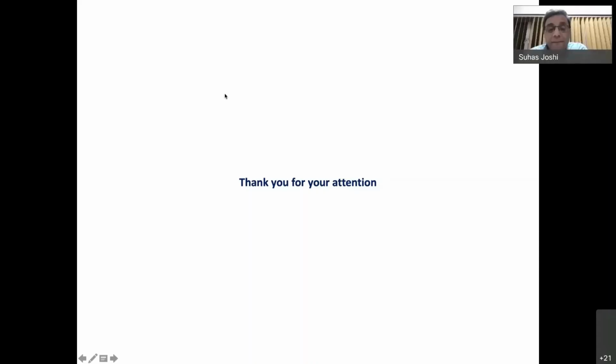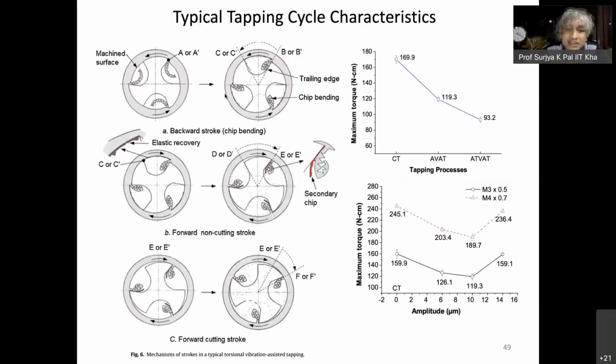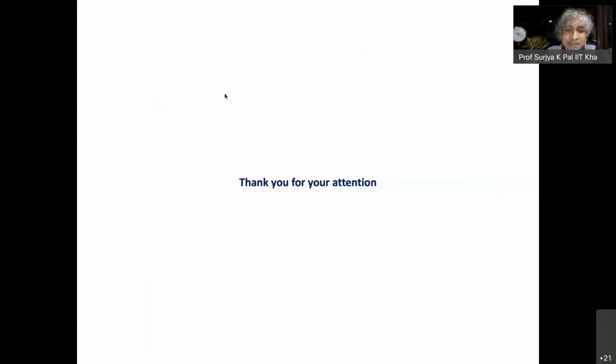Sure. So you have done experiments for different compositions, different environments, and also the process parameters. And you have used the quick stop, chip freezing mechanisms. So how fast is this mechanism's engagement and disengagement, and how do you control that, to ensure that the heat which is getting generated, the process gets repeated uniformly?